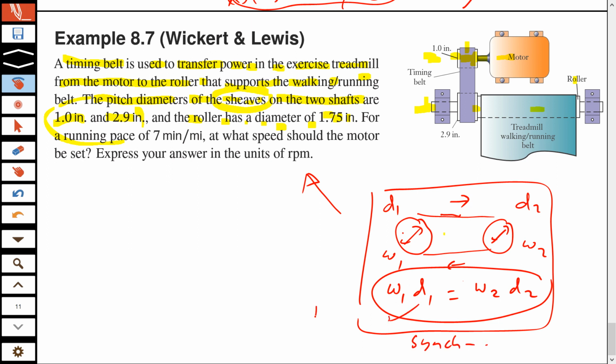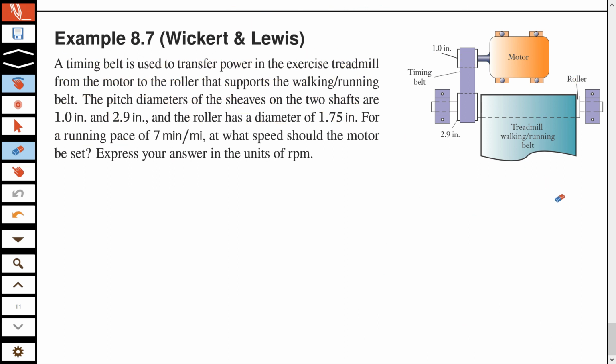यहाँ पे you will not see the number of gears because ये teeth का equation नहीं है. जब आप gears के लिए equation लिखते हैं तो you have a relationship in terms of ng and np. आपको याद होगा omega 2 omega 1, और यहाँ पे आप लिखते हैं n1 over n2. यहाँ पे n1 n2 का चक्कर नहीं है क्योंकि पुलीज है, पुलीज में टीथ नहीं होती, पुली में जो है ना उसका डायमीटर होता है. So that is something we need to keep in mind for this question. क्योंकि इसमें कोई नंबर ऑफ गियर्स हमें नहीं दिया हुआ, नंबर ऑफ टीथ हमें गियर्स पे नहीं दिया हुआ.